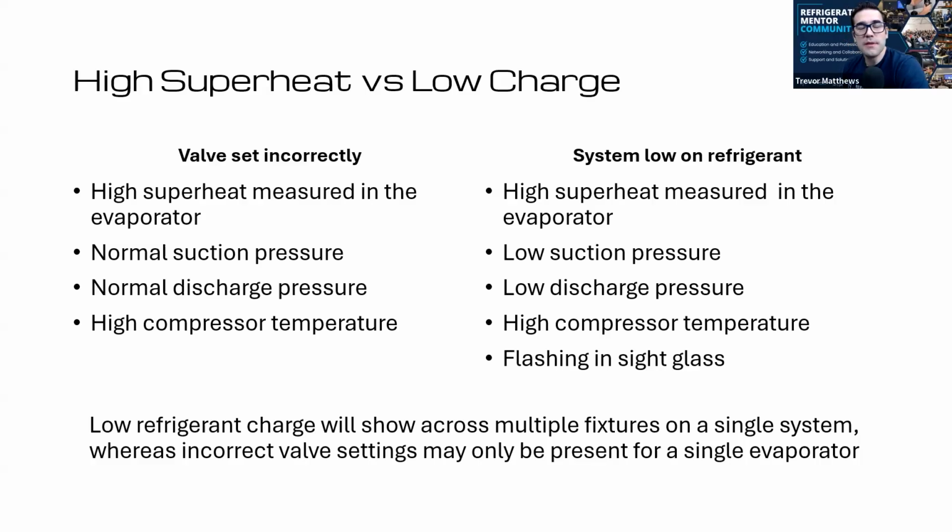So the flash gas bypass valve or the receiver valve is functioning, and all of a sudden power's killed. Potentially the valve could get out of line with where the controller thinks it is. Exactly. It doesn't know where it is, because if the power's not off long enough for the controller to drive that valve fully to zero, it can go out of calibration. So it's always worth checking they're calibrated.